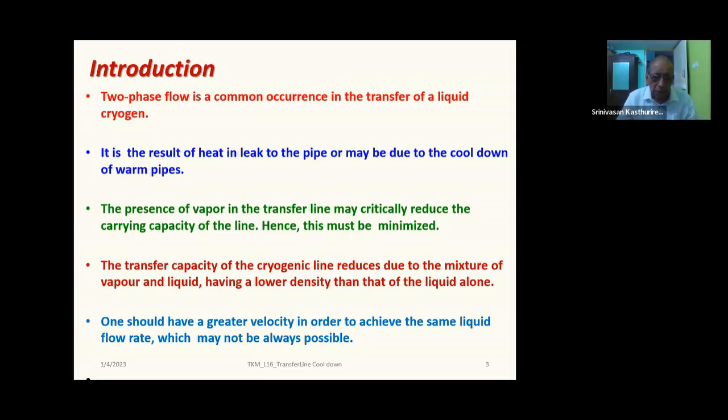It can be a vacuum insulation, or it can be a powder insulation, or it can be super insulation along with vacuum, etc. So the general concept of a transfer line is that you have a liquid carrying line surrounding which you have a vacuum jacket. Okay. That's the normal arrangement of a transfer line. As in any case, you will have to have appropriate bends or T-joints and various other things, or valves, safeties, etc., which will also be incorporated in the line.